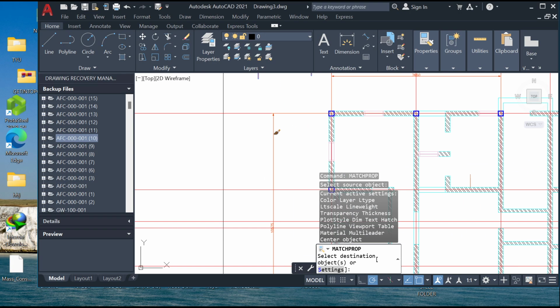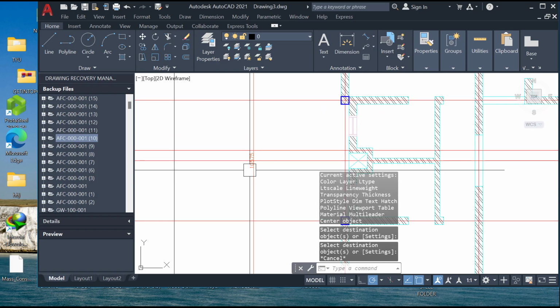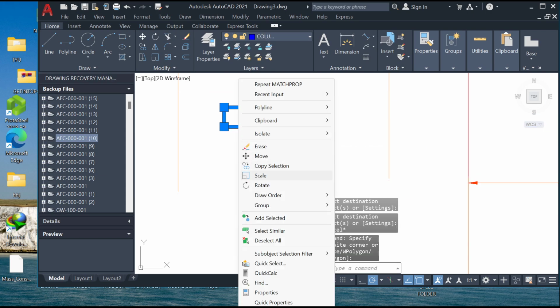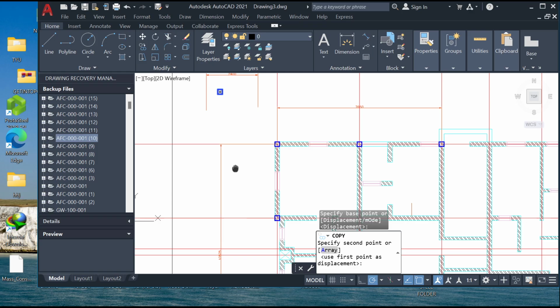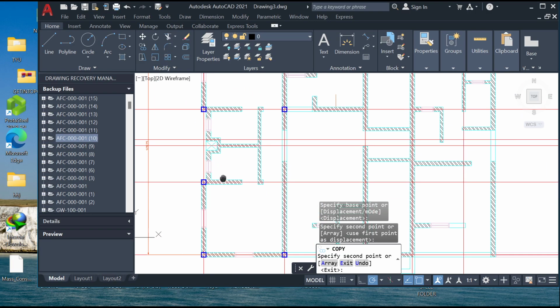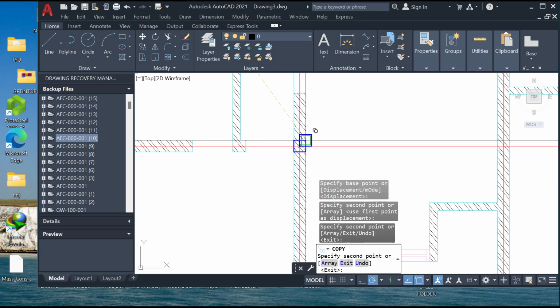Now let's click on this. You see, this is even almost 11 meters. So we need to introduce a column to break the span. Remember I said that it shouldn't be more than 5 meters. So yes, we can have a column here. It's inside the wall, and we can also have a column here.